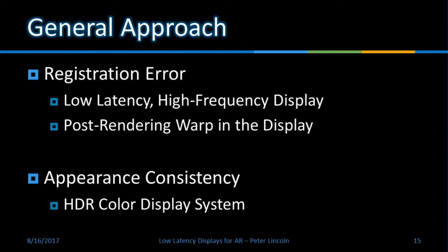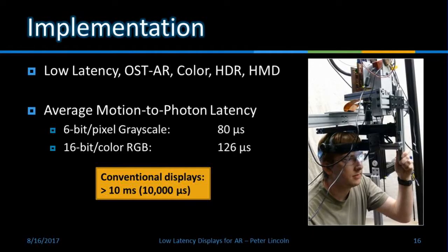First, I wanted to resolve registration error. And for that, I needed a low latency, high frequency display, and I performed post-rendering warp in the display. Second, to maintain appearance consistency, I needed an HDR color display system. And so I did. I created a low latency, optical see-through, augmented reality, color, high dynamic range, head-mounted display.